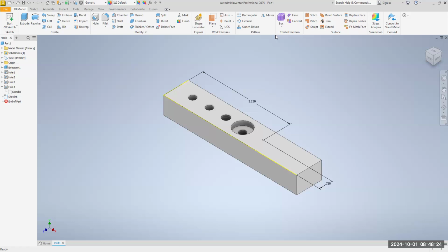Sometimes you have a rough surface. You don't want to tighten down on the head of the screw. It's not going to seat properly. That's why you want to make a nice, smooth, squared surface, okay? And that's what we're doing.